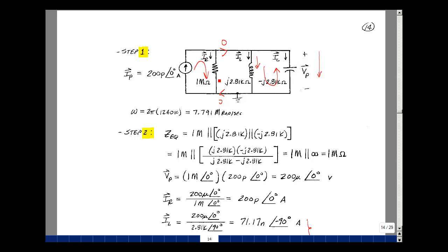So at resonance, we have actually the largest value of impedance that we're going to have. The lower and higher will be going down in value. So we have the maximum resistance at resonance. If you have a weak signal coming in, think of it as a current, all that current is going to flow in here and produce the largest voltage. And we're going to use that then to sense the radio station and then to do some demodulation and then play eventually the signal that was received.